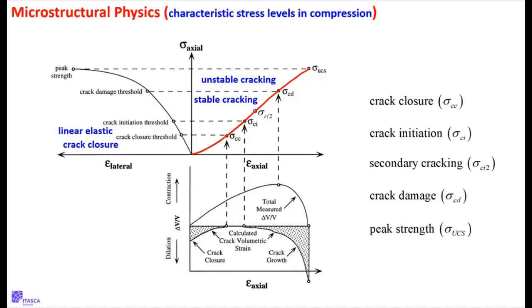That's all they typically measure directly in the test. They might wrap a chain around the diameter of the cylinder, and they can measure the elongation of that chain. That elongation of the chain can be related to the lateral expansion of the cylinder. Or they put, well, there's all kinds of different experimental ways that this is measured.